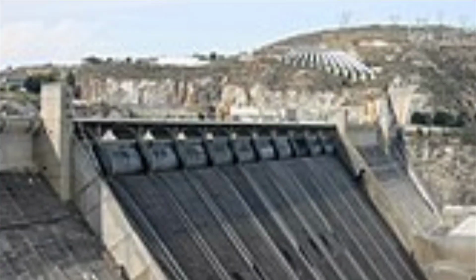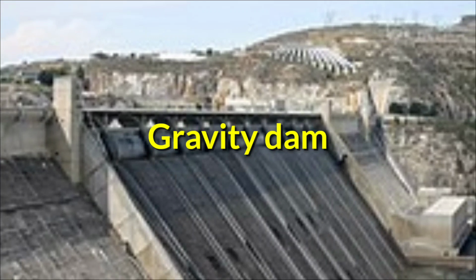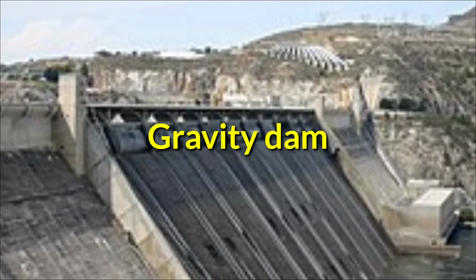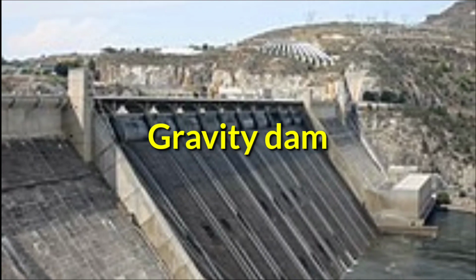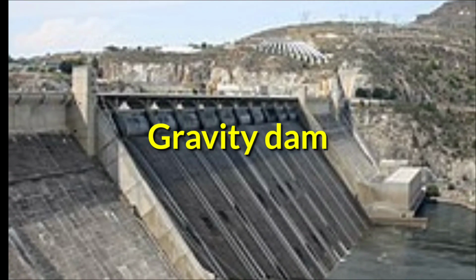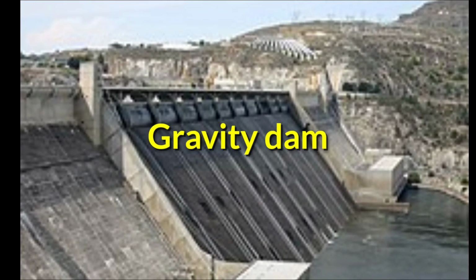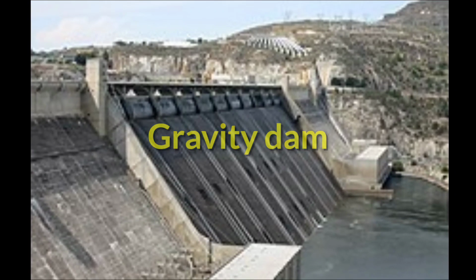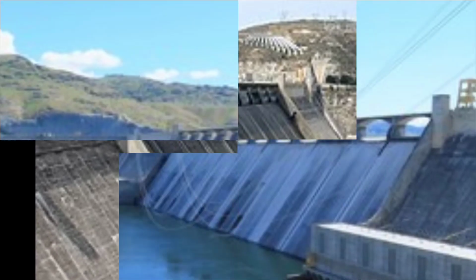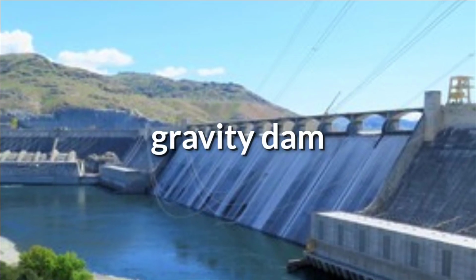The next dam in this category is the gravity dam. A gravity dam is a structure designed to withstand loads by its own weight and by its resistance to sliding or overturning on its foundations. Newer dams of this type are typically composed of unreinforced concrete or monoliths with seals at the joints. But in past centuries, many gravity dams were constructed of stone masonry.